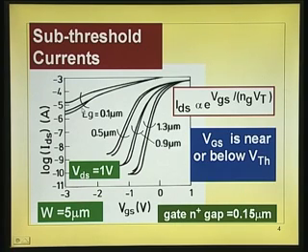The gate length varied from 1.3 micron, this curve, 0.9 micron, second curve, 0.5 micron here, 0.1 micron. This is about the range that they got. So, they have put some number of curves with the range, okay. But you can take it as one curve if you are putting an average value. So, you have got 1.3 micron here, the gap between the gate and the N plus region is 0.15 micron. You are cutting it very sharp. So, for those devices it is like this. In fact, you are talking of a really short channel effect.